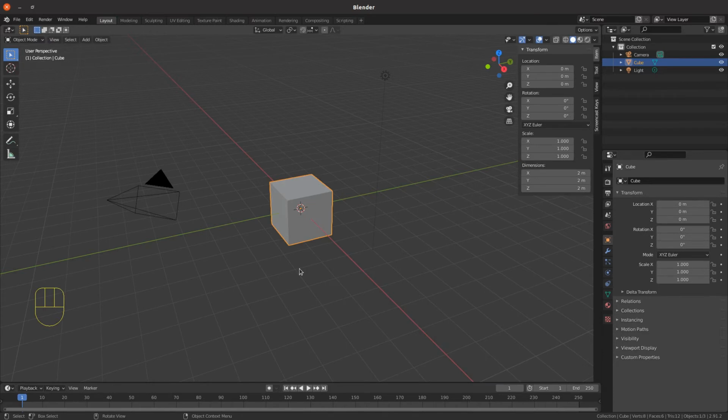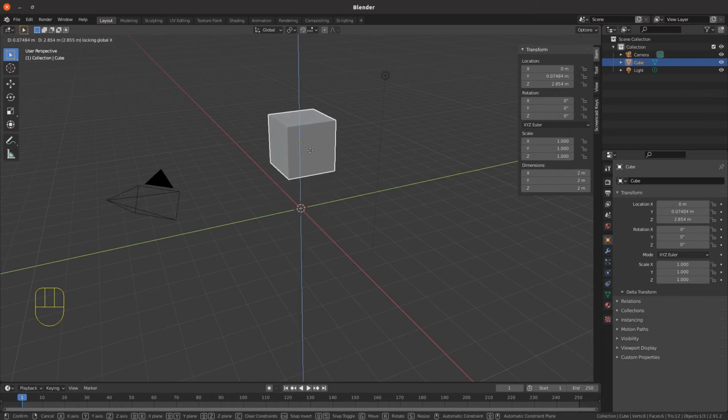The next option, using the shortcut keys with move, is to grab. So with the cube selected, grab the cube. This time, if we press Shift X for the axis, it constrains the movement to move on the Z, Y plane only. And you can't move it along the x-axis, it just moves along the plane that's perpendicular to the axis that you've pressed Shift to.